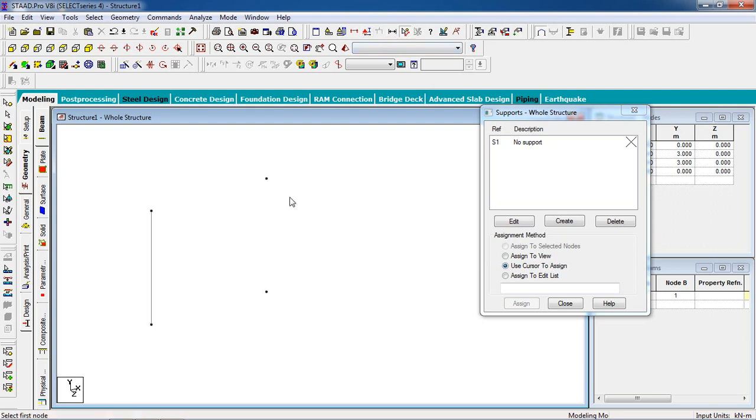You may think that the minus will affect the design, but it does not. Dimension will not give any trouble for the design. The design is based on the support property, member property, and the load. Check the dimension 3 meter. Okay, remove it and add the nodes by add beam. Now there are 2 columns and 1 beam.